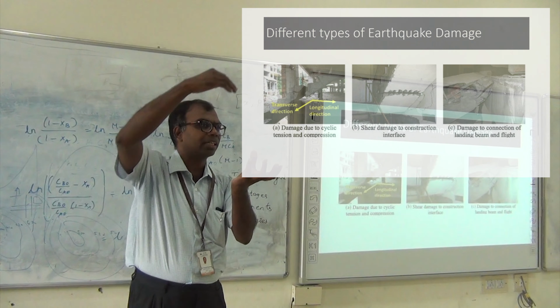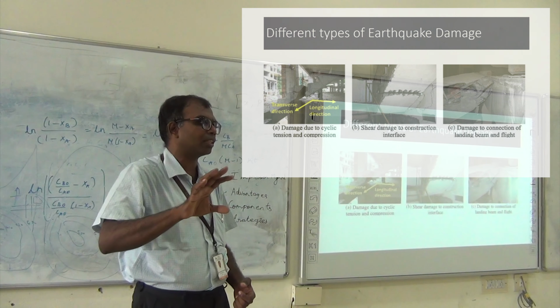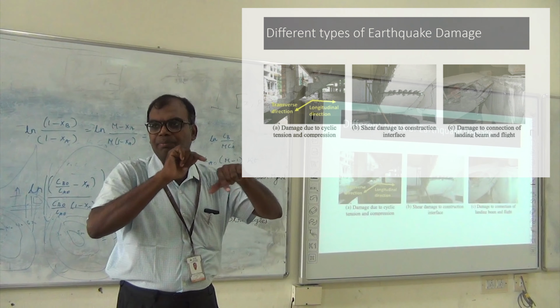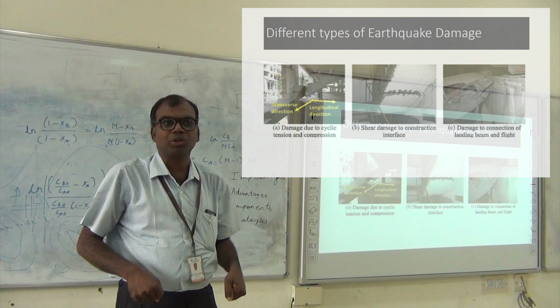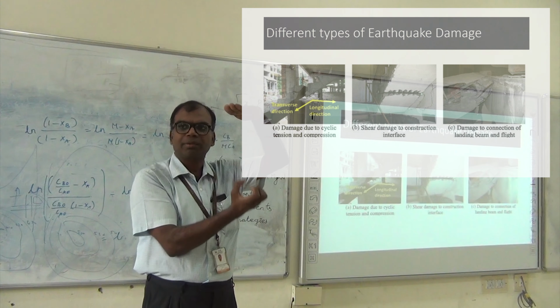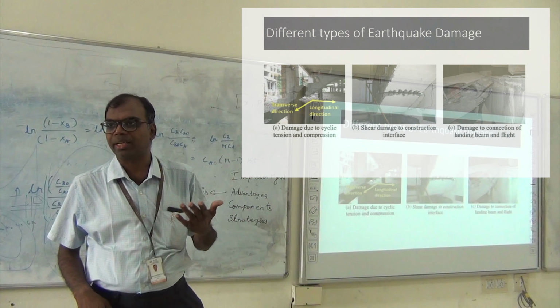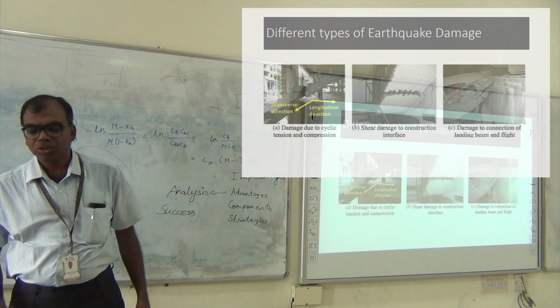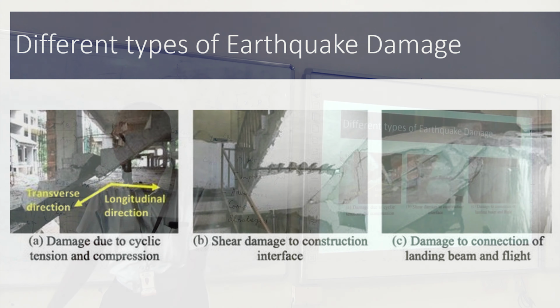See, you take the same scale and keep loading it with very large loads, and you will find it takes a very large amount of force before it buckles and breaks. On the other hand, if you are continuously doing a cyclic motion, even though the load is very less, I'm keeping a mass, vibrating it, keeping on vibrating it, at a very low load itself it tends to fail. This is the problem with fatigue. Whenever there's an earthquake, you're going to have a cyclic load.